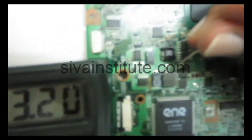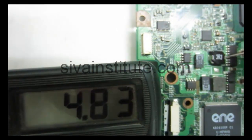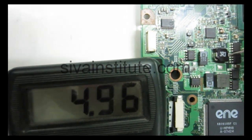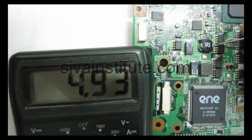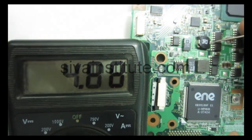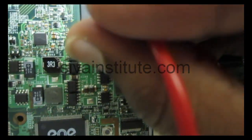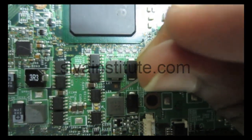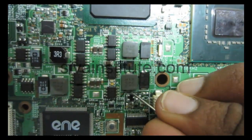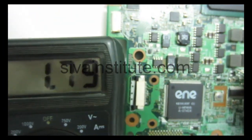Next, see at that coil 5 volts. See 5 volts. 4.7, 4.8, okay, 4.9. This voltage is okay. 3.3 volts and 5 volts is okay. Now we will check the memory supply 1.8 volts. 1.8 volts at this coil. Okay, 1.8 volts memory supply. 1.79, that means 1.8 volts.